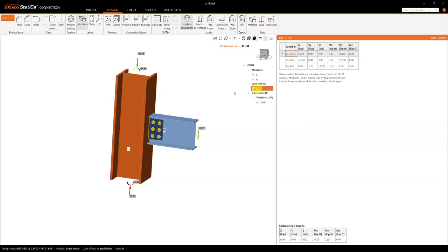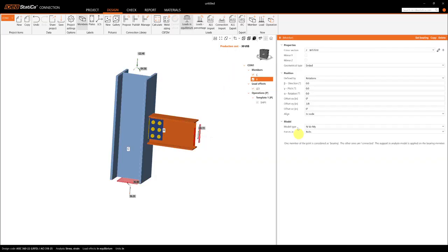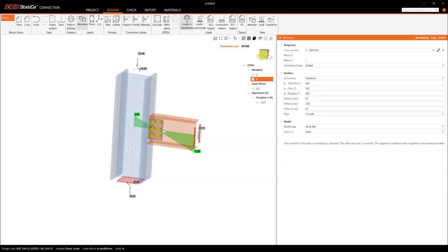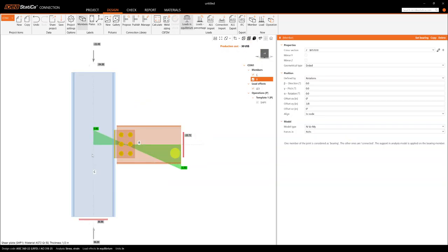And then here on the loads, you will see that you can apply the forces on the members. This is a graphical representation of the forces, but in reality, where the force is located is where it says here, right? When you click over the B member, it's saying it's applying at the bolts. To look at that position of the force, that is basically shifting the force where you want to assess that shear force.